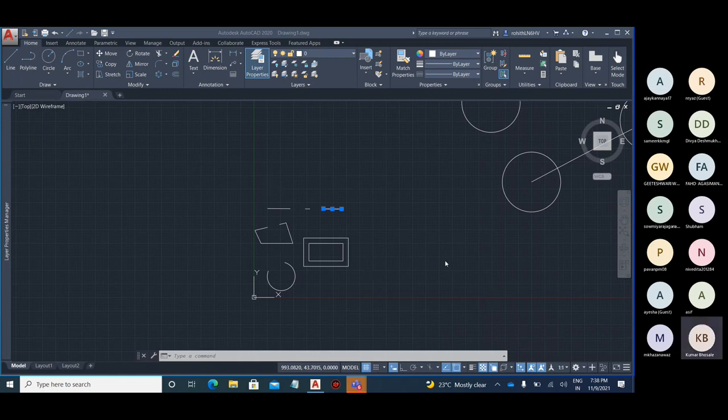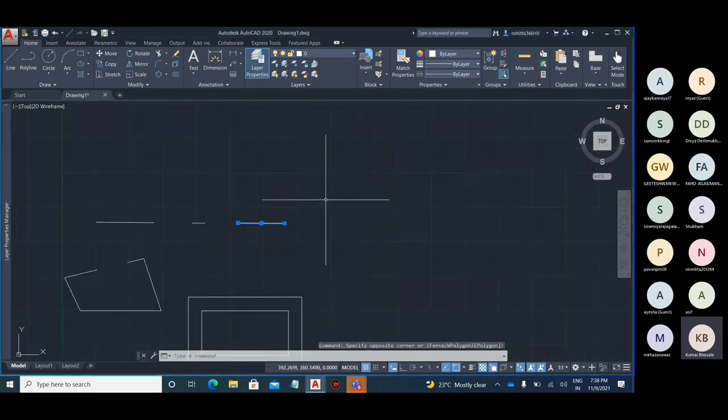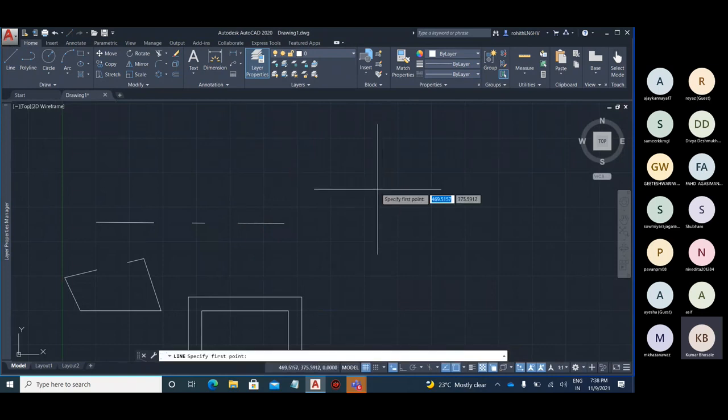Okay. Now let's talk about what dynamic inputs are. Have I discussed the dynamic input with you? No, sir. Okay. So dynamic input is what you see every time you're trying to give an input. When I click Line, you can see near the arrow there are two boxes, and there is a command prompt that says Specify first point near my crosshair. This is known as dynamic input. So directly at that position, I can give my inputs. Otherwise, the second inputs you can give by giving the details in your command prompt.